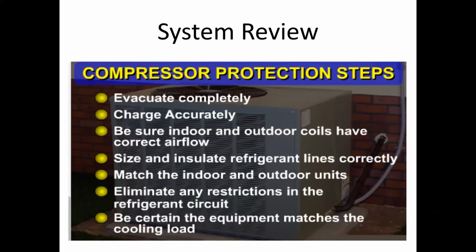If your indoor is not moving the right amount of air, or your outdoor is not moving the right amount of air, your charge isn't going to be right. The outdoor could be not moving the right amount of air because you have a dirty coil. It could also be because it doesn't have the right fan blade on it, especially on a system that's been in for a little while, where maybe somebody puts an aftermarket fan blade or an aftermarket motor on it. That'll affect the amount of air being pulled through that outdoor coil.